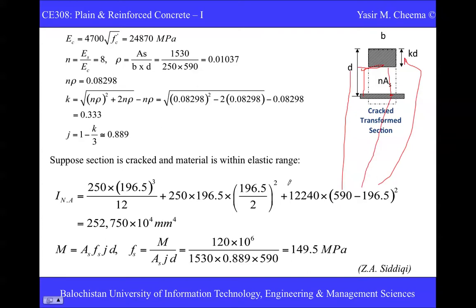So all this stuff is the area and the moment of inertia. One thing more I want to add is this: we didn't write the moment of inertia here. You see, it is just area and it's just AD square. Actually we neglected the moment of inertia because this thickness is very small. If we take the moment of inertia of this thickness, it will be a very small amount, so it's just negligible. So we just remove this value and we just write AD square. Okay, hope you can find out this numerical value.